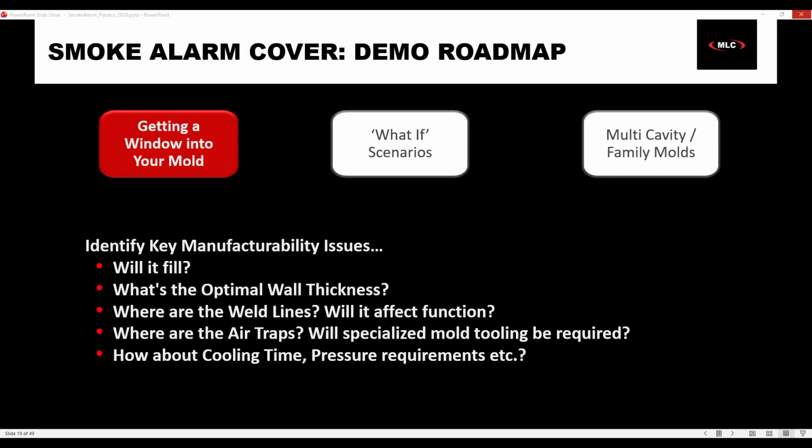One other thing I like to take a look at is there is an item as a result that says ease of fill. Now, this is like a feasibility test. How feasible is it that this is going to fill very consistently over time? So you're looking for green. So green is good. We'll see a couple scenarios later where it pinpoints areas that may not be consistent that we should be concerned about.